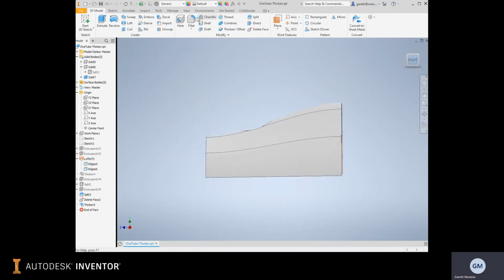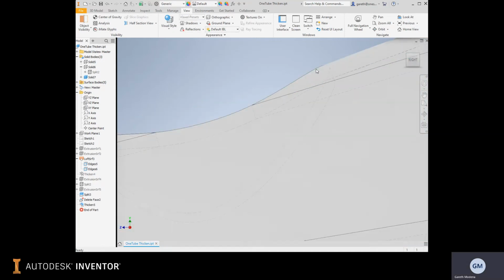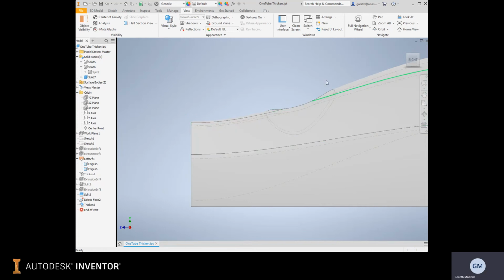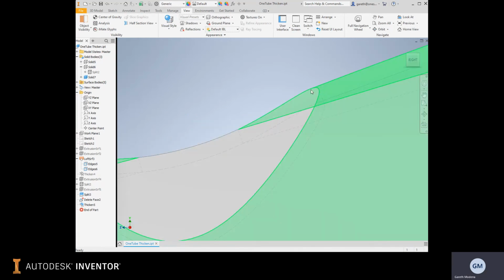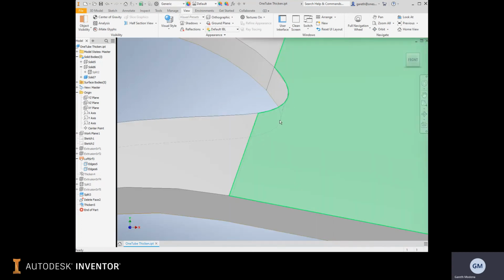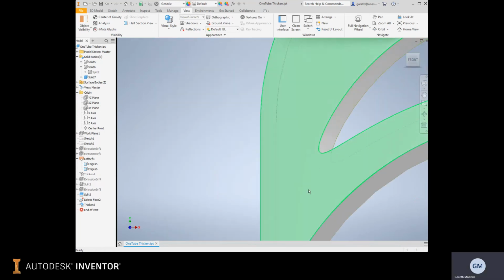And by default, if we just switch to the views, hidden details, that won't work. It'll create a projection perpendicular to that surface all the way around that cavity. So if you were looking for a linear vertical cut, you could have just used normal extrude, but this is specifically perpendicular to the surface. You can also see its orientation according to the curvature of the surface.